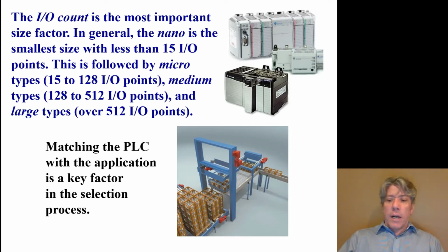Now, very often what you'll find is that you'll think you only need a small number of inputs and outputs, and when you start building the machine you realize that to make it work you're going to need a whole lot more sensors and a whole lot more output devices. So it's always very important to think ahead with the PLC and just leave yourself some room for expansion.